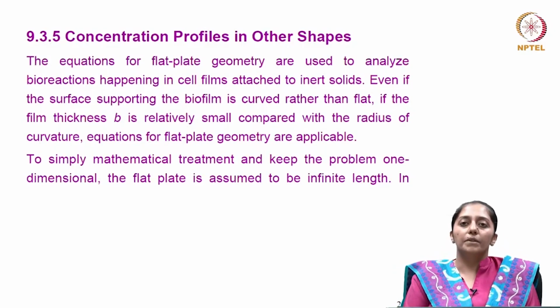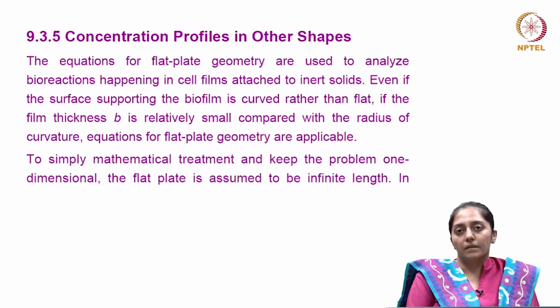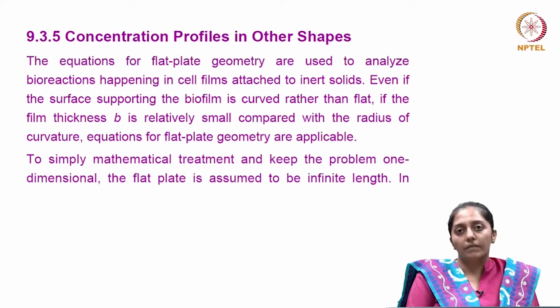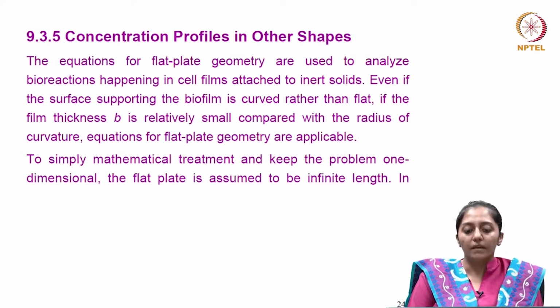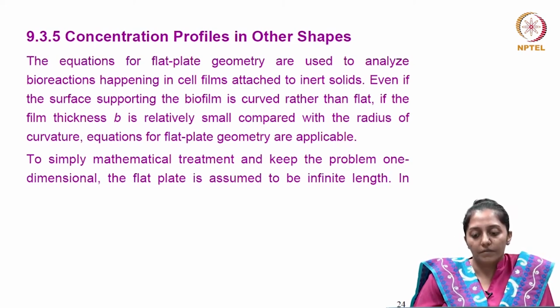Now, if we need to determine, so we have been assuming from the beginning for ease the particle shape as a spherical particle. Now, let us see how will the concentration profile change with other shapes which we come across in various bioprocesses, like your biofilms, where the geometry will be like a flat plate. So, the equations for a flat plate geometry will be used to analyze the bioreactions happening in the cell films attached to inert solid surfaces.